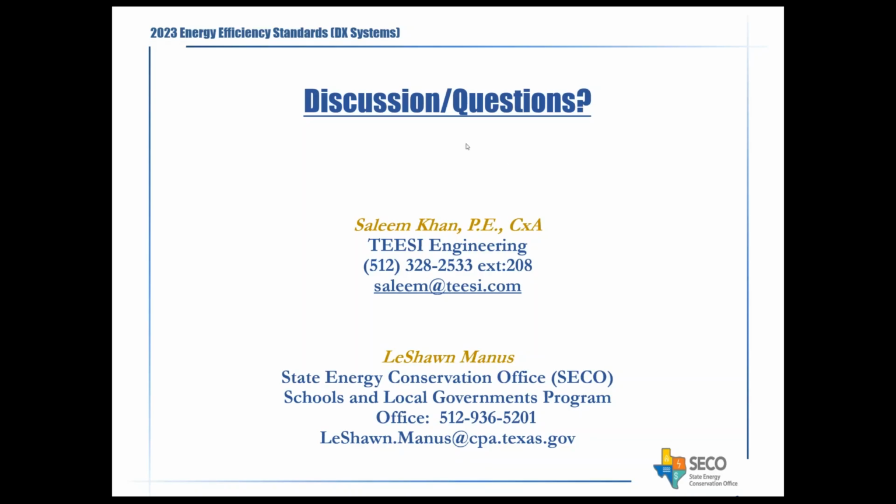Sorry, I was just having a hard time going to the last slide. We have very little time left, a couple of minutes. There was one question, and I will look into that more and then answer everybody with more specifics. The question was, will the lubricating oil be the same for replacement of 410? I suspect there are some differences. That's why they're recommending change out of the indoor and outdoor unit, and ideally a new refrigerant line, or at least vacuuming all the oil out from the whole system. But I'll get that answered also.